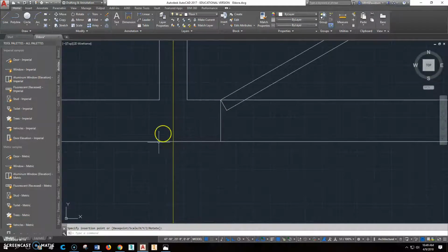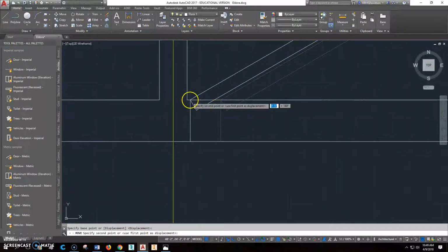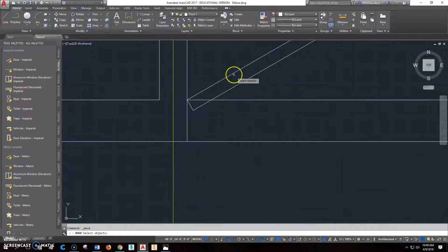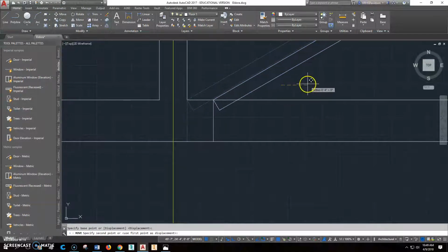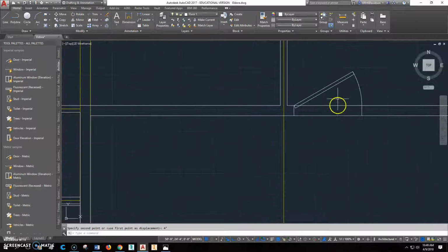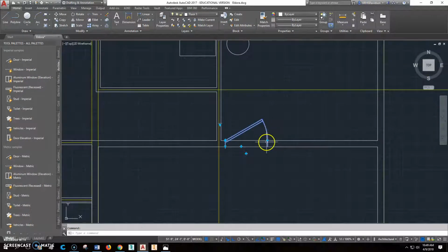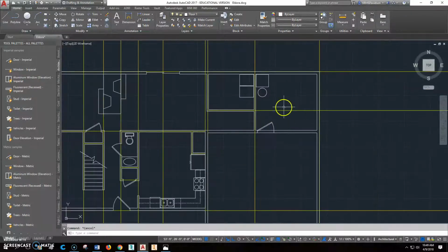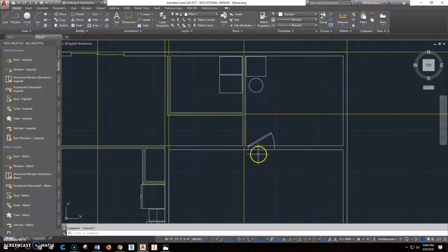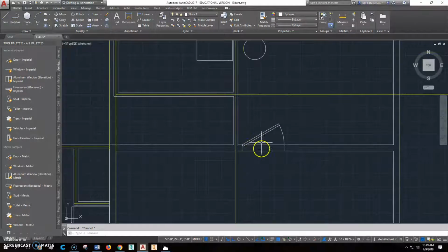So, oops, it didn't snap the way I wanted it to. So I'll click move. Come down here, put that in there, and then I'm going to move it again. And I'll move it out 4 inches. That's a wide door. You know, I probably want a wide door. No less than 3 foot. So 3'4" is probably good. That way we can get equipment in and out of our shop. And we'll open it inward from the garage. That's just, it tends to be what you do.